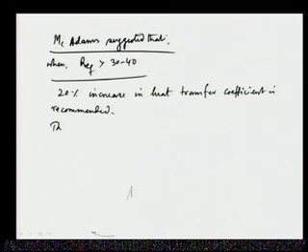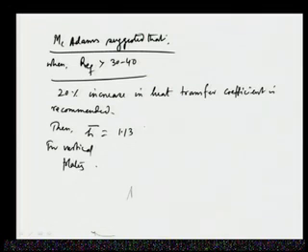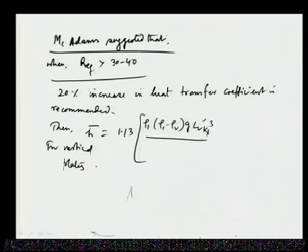Then H bar happens to be 1.13. So, with a 20% increase, H bar for vertical plates is 1.13, and the rest of the things remain the same, rho L into rho L minus rho V, and then g into L V into K L whole cube by L into mu L into T infinity minus T W, whole to the power 1 by 4.